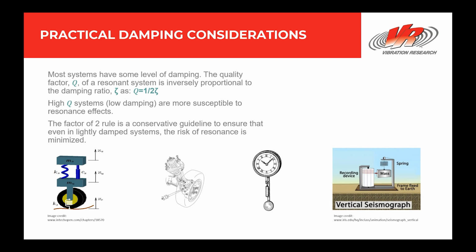And then the last case, overdamped, when zeta is greater than 1, we could think of really heavy door closers, so heavy industrial or vault doors with strong closing mechanisms, return to the closed position very slowly and steadily without bouncing. Also, electronic filters, so certain low-pass electronic filters designed to remove high-frequency noise from signals may be overdamped, resulting in slower response times to changes in the input signal.